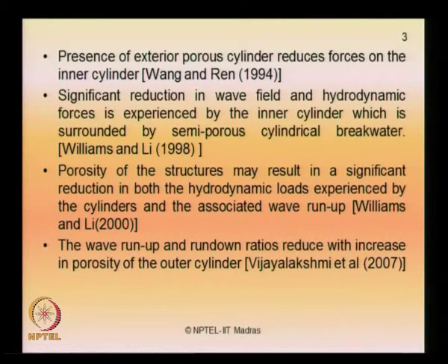It is shown that the wave run up and run down ratio reduces with increase in porosity, but there is an upper limit for this. You cannot make the outer layer totally porous or totally pervious, as then the effects get completely nullified. So there is an upper limit of this porosity, which has been studied and examined by Vijayalakshmi et al. in 2007, and literature shows that wave run up and run down ratio reduces with increase in porosity.